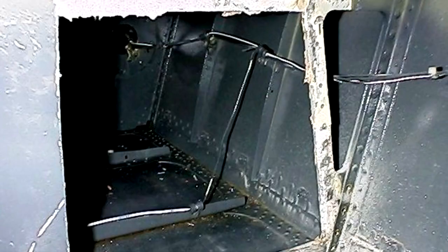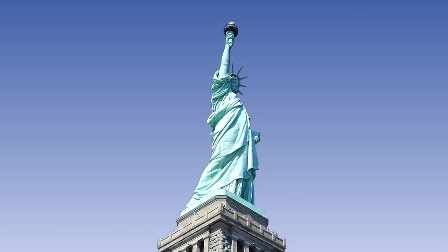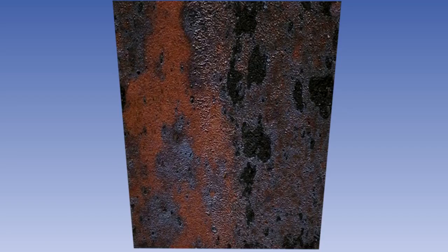The surface of aluminium or magnesium can become covered in white to grey powdery deposits. On magnesium, there may also be deep pitting of the surface. The surface of copper and its alloys may become covered in blue-green salt deposits. Surface corrosion is the least damaging. It is relatively easy to spot, so it can be identified and dealt with at an early stage.